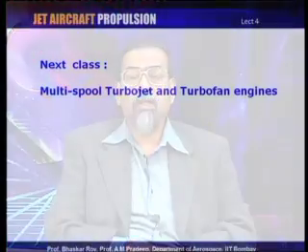And this is another facet of a bypass engine, even if it is a very simple single spool turbofan engine as we see in this picture. So, the bypass engine added to the basic version, and we have seen reheat added to the basic version. The reheat gives you more thrust, the bypass gives you more efficient thrust production and lower SFC, and a byproduct of it lower noise. So, we have discussed various kinds of basic jet engines.